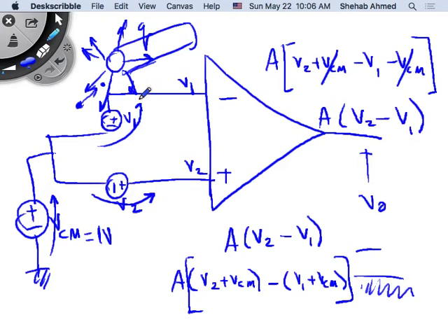This signal has coupled, and both wires are moving together. If you made the wires very different from each other, away from each other, then this external signal may couple to them differently. But let's say you did your job as an electrical engineer and brought the wires together and twisted them, so they see the same effect. Especially after you twist them, every point on the wire will probably see the same effect.